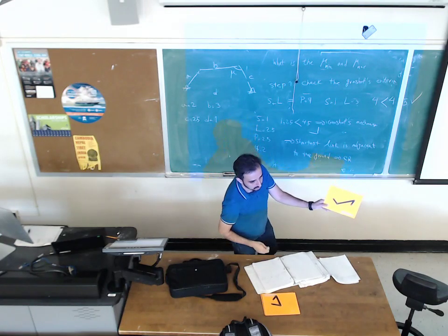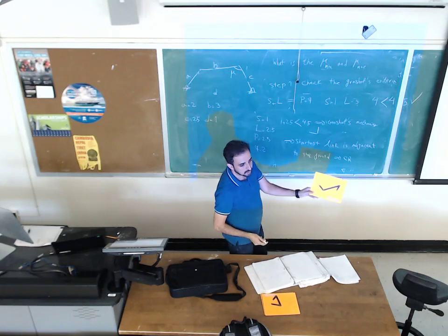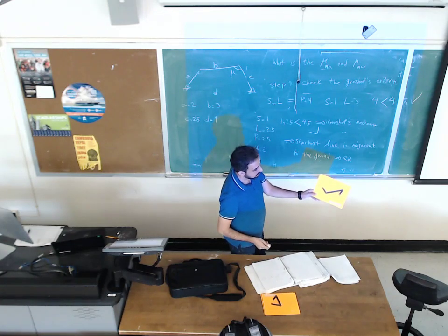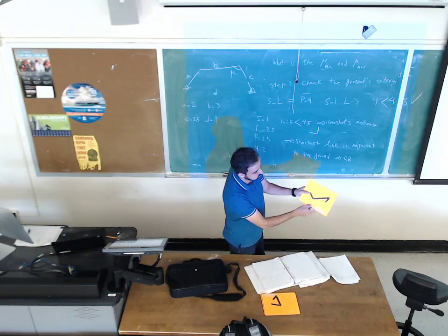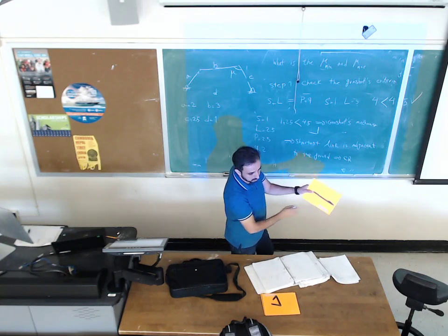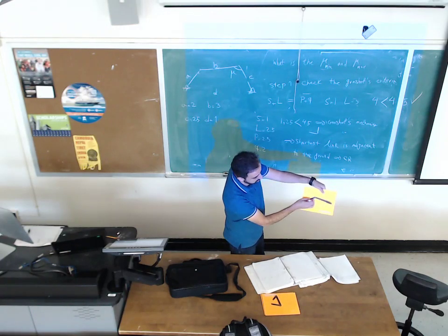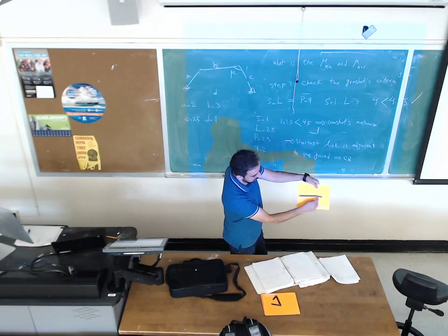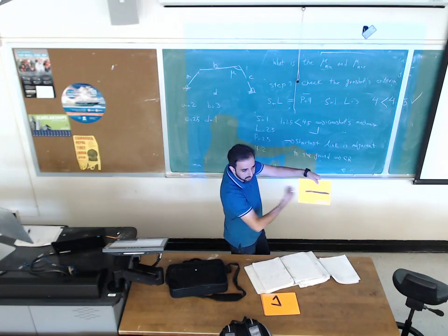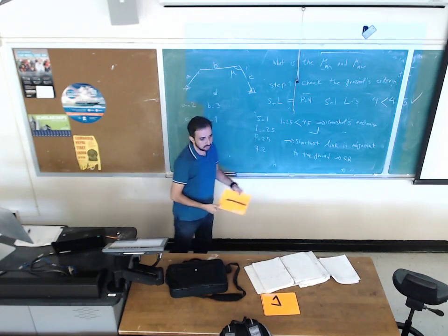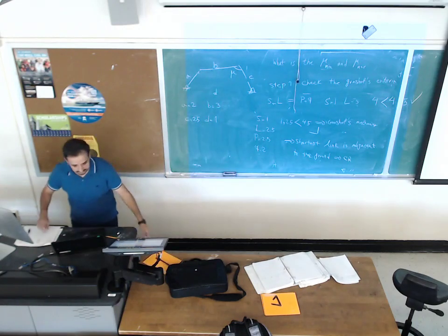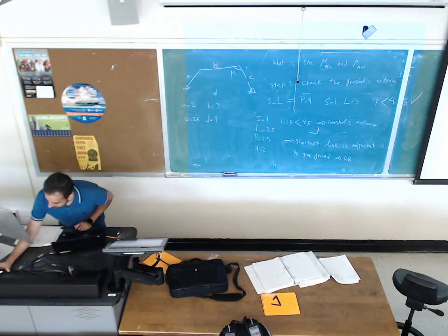Well, there would be two different transmission angles in that case, right? Because there are two scenarios. So if there was a question like that, you would like us to find them both. For minimum and maximum? Yeah. For the minimum, it's going to be 0. For the maximum, it's going to be 180. This angle is 180, because everything is going to line up. Okay. Make sense?